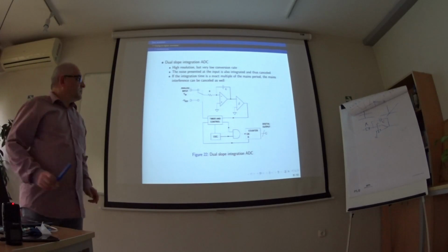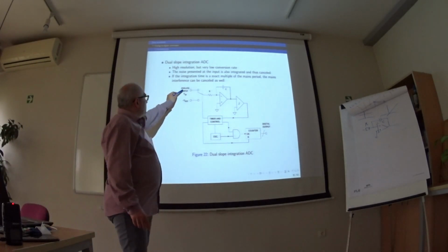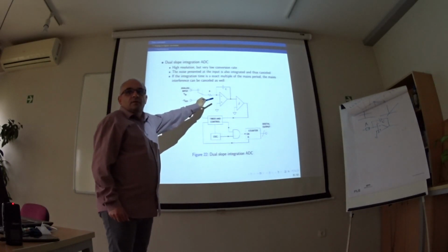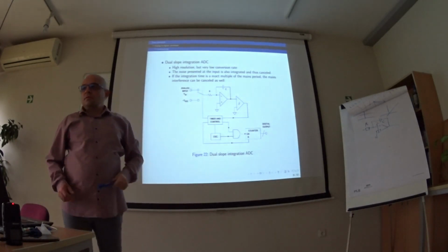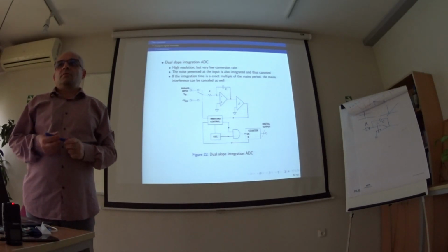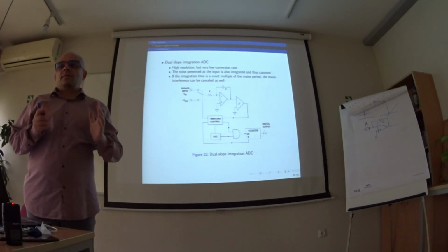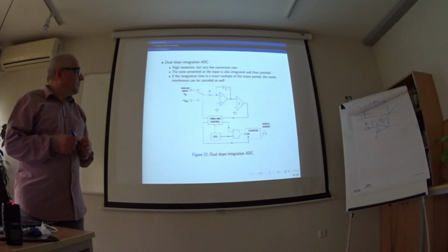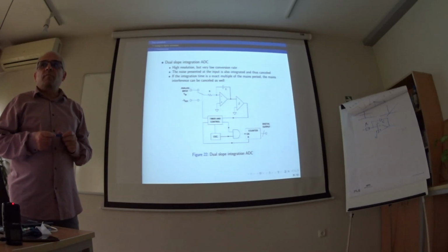An additional benefit: if we have noise in our input, this noise is also integrated. When we integrate, the noise floor decreases. We can cancel the noise. Also, we can cancel the interference from the power line.